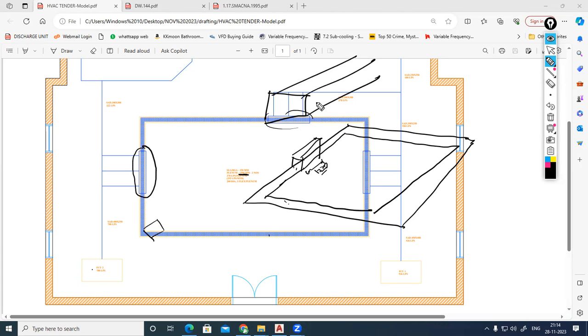We have to design it when we are studying air terminals; we can study that. Then from the duct side, 3 flexible ducts will come. The diameter of the flexible duct is 200 mm. Here it is 200 mm. So a 200 mm flexible duct will come. This is our first flexible duct. This is our second flexible duct. This is our third flexible duct. Then through the duct, the cold air will be coming. Then through the flexible duct, we can distribute the air through the plenum. Okay.